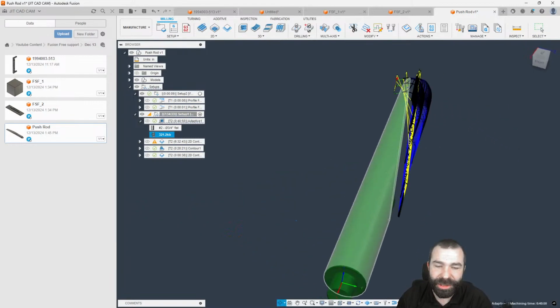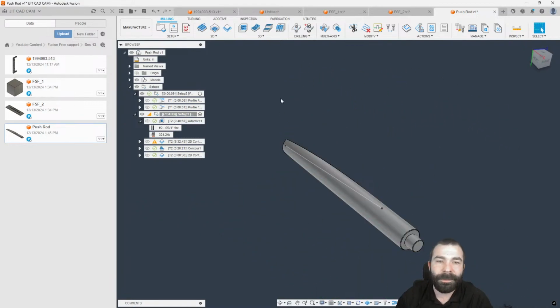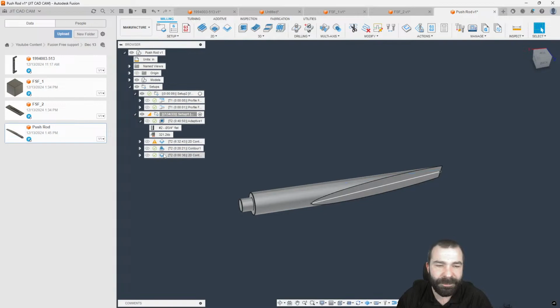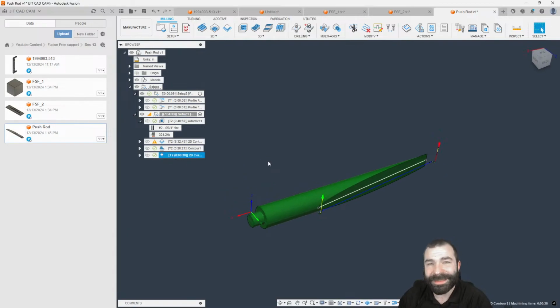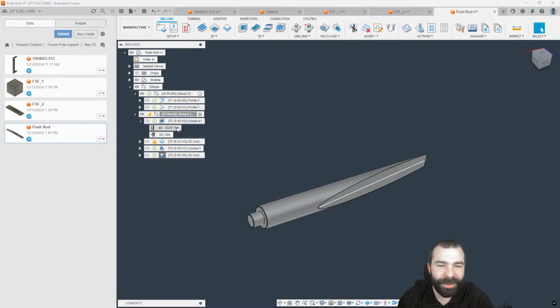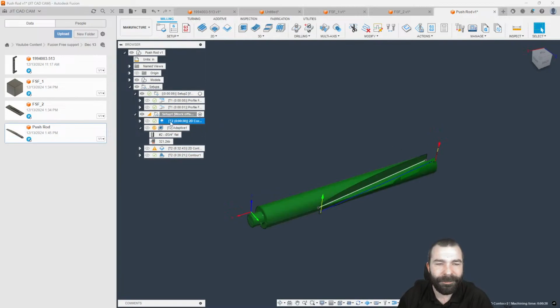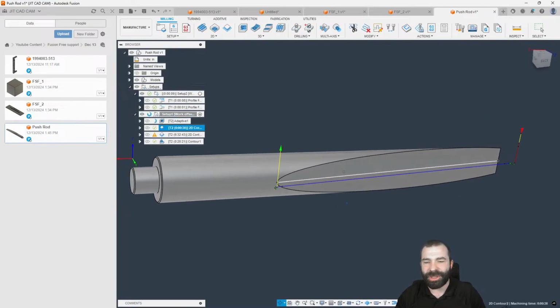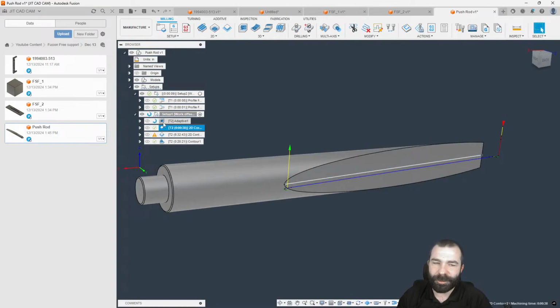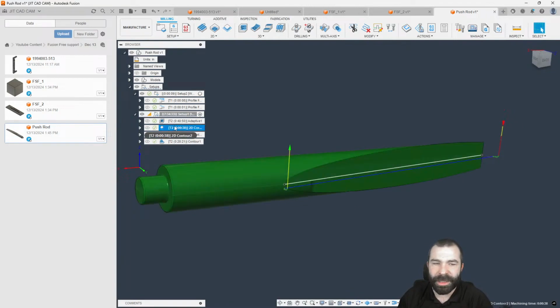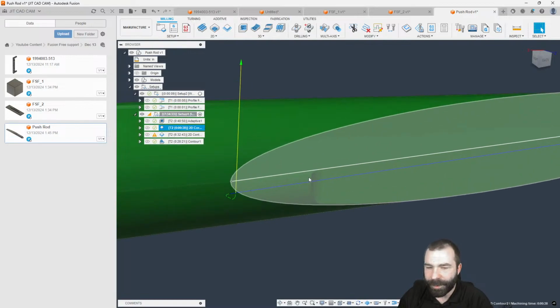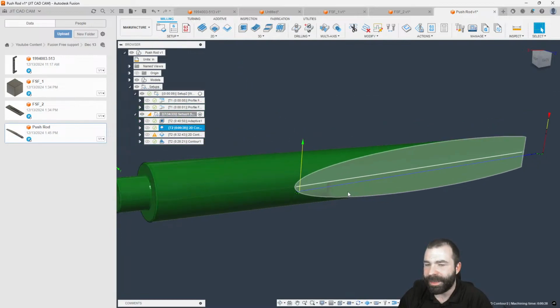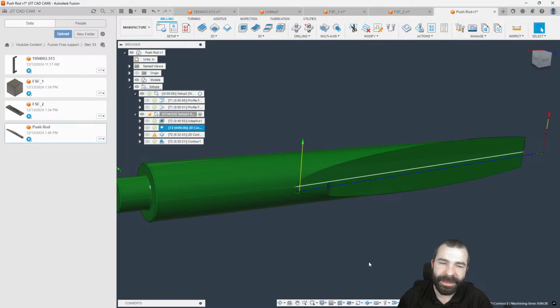So this is actually a good part to look at. I'm going to go ahead and machine, and in this case, I think this is probably one of my favorite things. I'm going to move this toolpath up for a couple of reasons. One, I want my clearing right after we do that adaptive. What I'm looking for is a visual representation for all of you. You're going to notice we're roughing this part out, we're leaving 20 on the walls, and then we're cleaning up the wall. You see this lovely little step still there because we're not machining all the way down that surface.